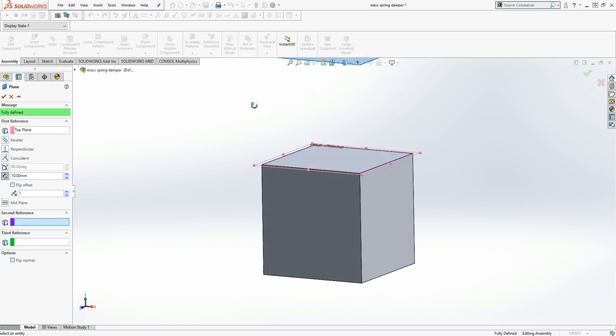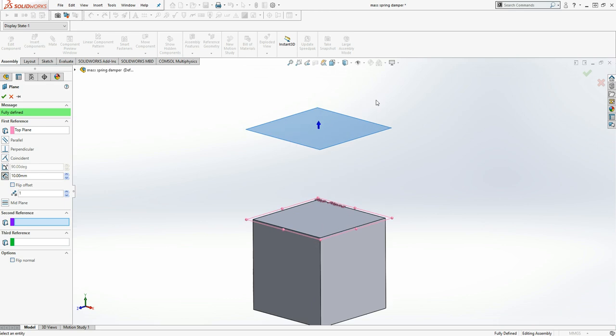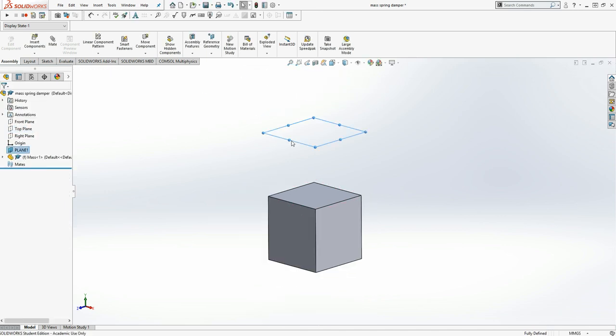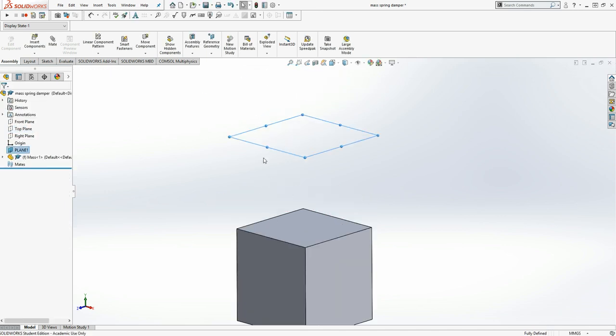So you notice this offset. It's offset of 10 mil. You can set the 10 mil to whatever you want. This is the start position of where we're sitting. So what I will do is click OK. This then confirms what my starting point will be.